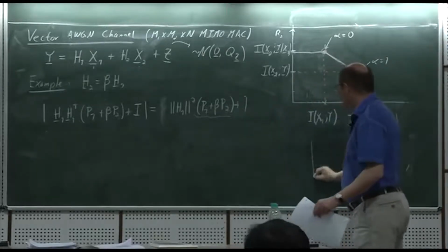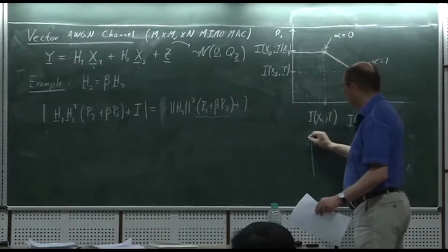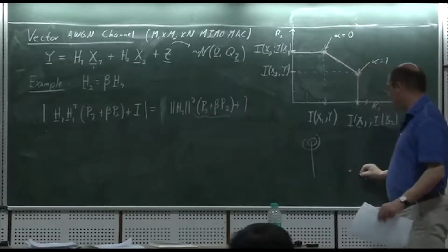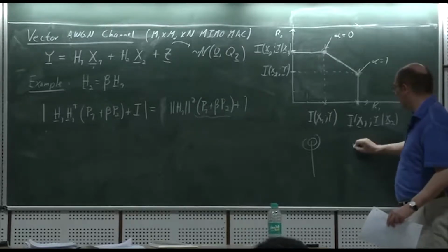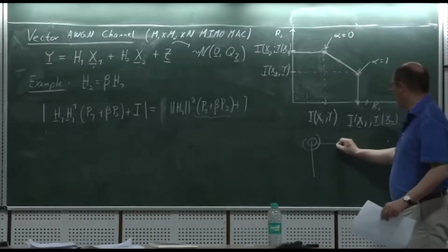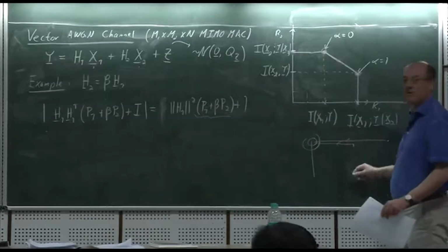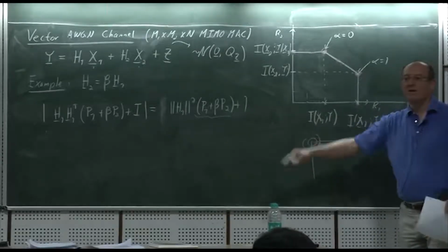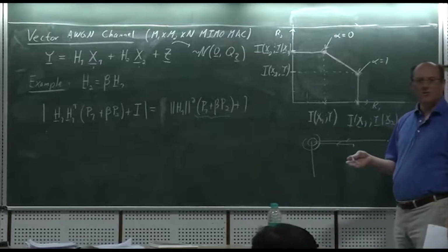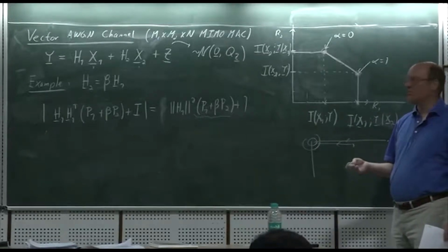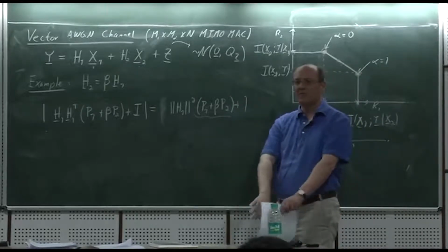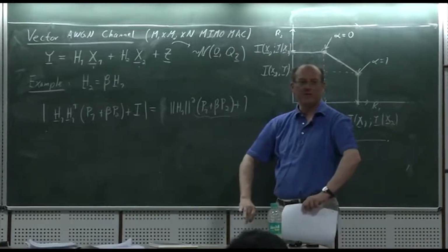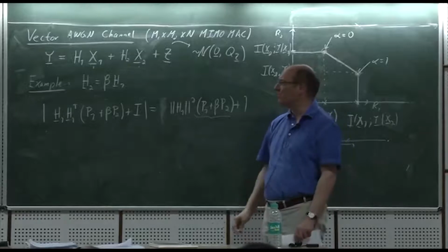Geometrically, this might correspond to a base station, right? And one user is here and another user is right behind him in a way, right? So maybe here and here, right? So the direction of the vectors is exactly the same. And that's not good in terms of getting good rates, because the trouble is here now we're not being able to use any spatial multiplexing at all, right? So we're not getting any spatial directions.